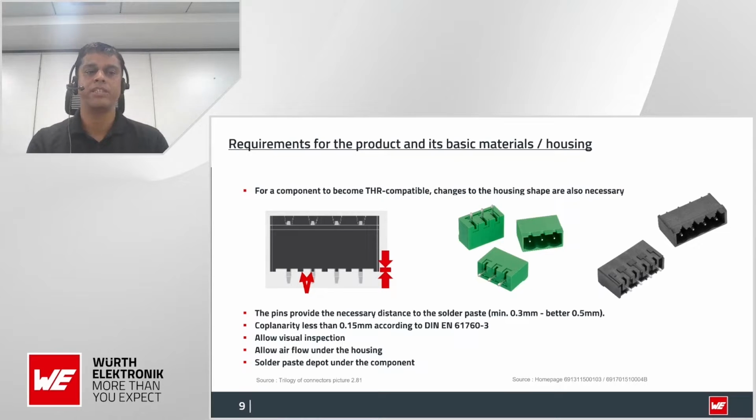And the second point, if you see this one, there is one more plastic peg between the pins of the connector. This also allows the connector not to touch the PCB. The reason is that any heat waves, I mean high temperature waves, are allowed to move freely in this gap. And the second thing is that solder paste will not be deposited under the component. This is very, very important. If any solder paste is deposited on the ground, that means the soldering has not been done properly. So this is about the design considerations we can have.